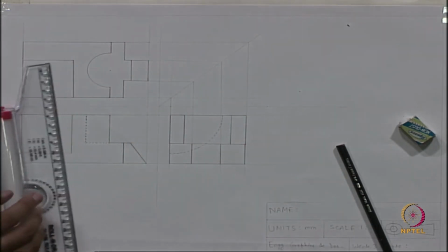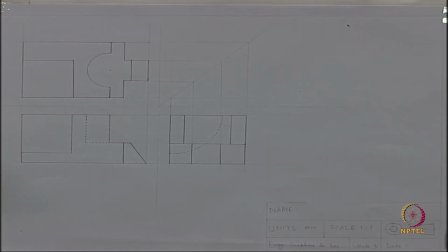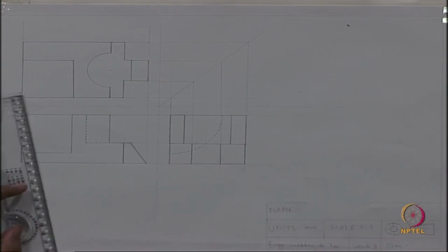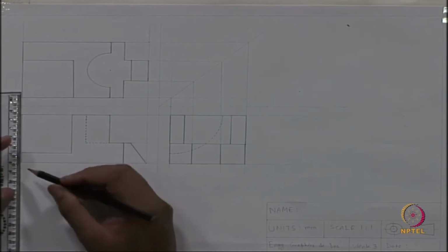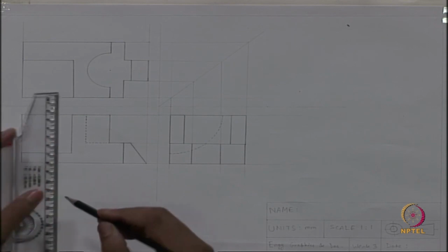See, now drawing wise we are done. Still one important thing is left, which is dimensioning. Dimensioning is very important. The aligned dimensioning system is mentioned here for our dimensioning. So, we will do that too. For our dimensioning we will use the normal H pencil because it will be light lines. So, first we will draw some extension lines from the figure. It won't touch the figure.